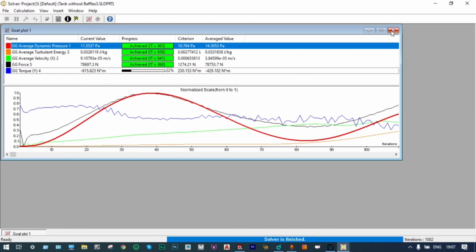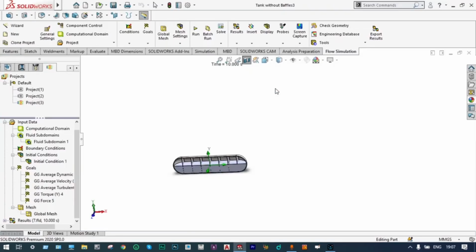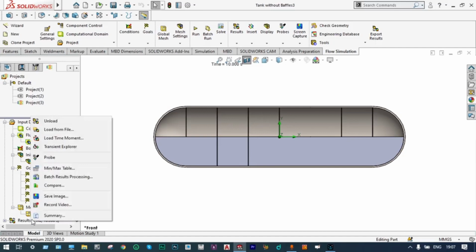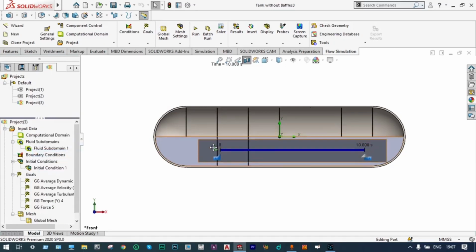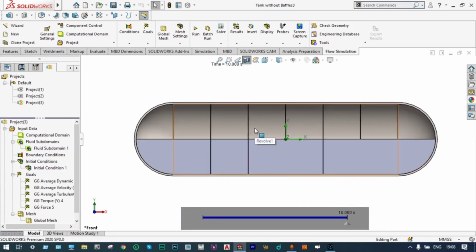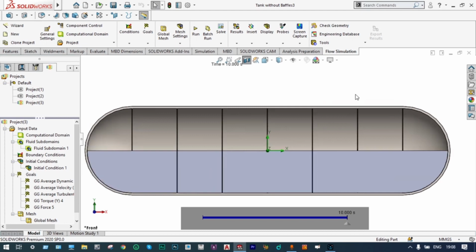Yeah, we can see the result from the cut plot to compare as well. Okay, let's close this and see the result in cut plot. Okay, this is a cut plot. To start this, we have to select the Explorer. We can drag this down and make the tank a little bit bigger, so it will be good for the solution effect.